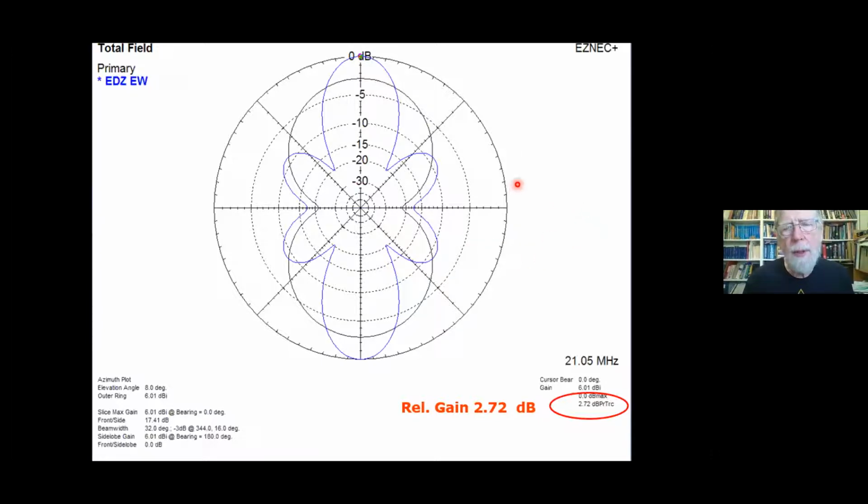Now we're showing the two antennas superimposed above ground, and we're looking at the gain at an elevation angle 6 degrees above the horizon, which is the elevation angle that you would need to do something like a triple bounce to Oregon from the UK. And what's the main difference between this and the previous one is you'll notice instead of having complete nulls down here, the nulls have been filled in a fair amount. But otherwise, the shapes are pretty recognizable and pretty much the same.